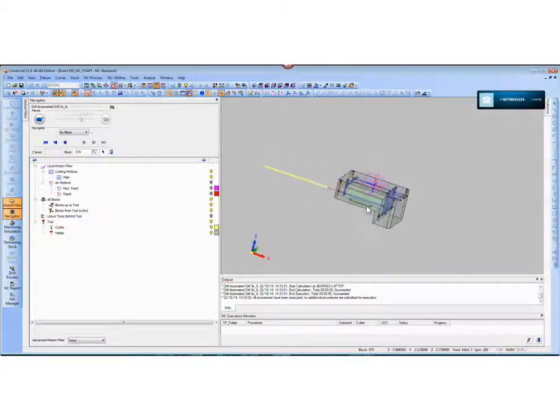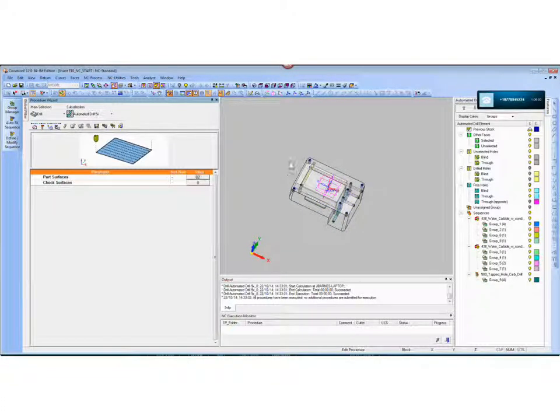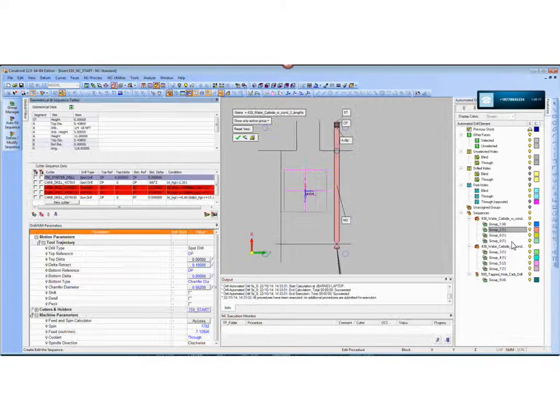Okay, so let's go into this one, and I want to explain a little bit better what kind of logic I set up. Let's take this long drill, for instance. Sorry, the long hole. I'm going to choose Modify Sequence so that you can see how I built it. So first of all, over here on the left, this is our geometric data. This all refers to the hole. And I can set a condition that says if there's stock on the top of the hole from 0 to 100, let that be a condition for it fitting to this geometry.